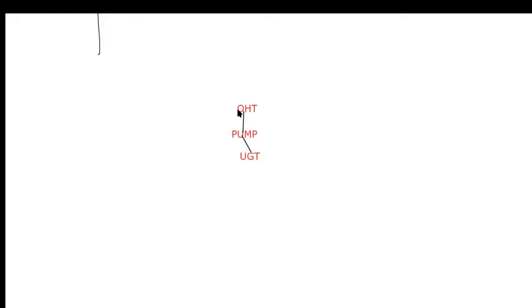in the washrooms that the ablution tap pipe size will be different. Then our regular tap will be there, that pipe size will be different. Then for our water heater, pipe size will be different, material also will be different. We might have noticed this. See, these are all things he needs to suggest to the client based on his consideration and calculation, and also based on the plumbing standards, which are IPC, UPC, and NPC.